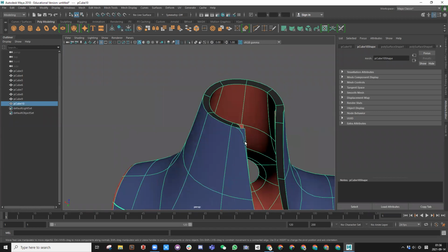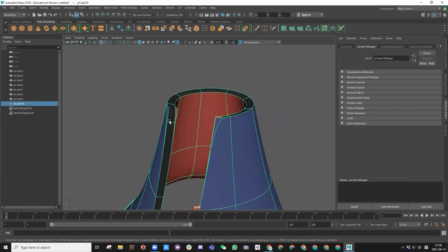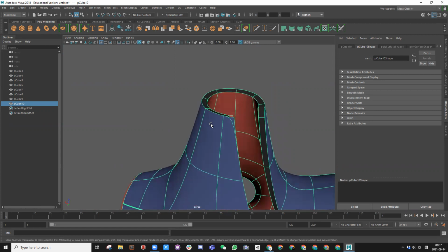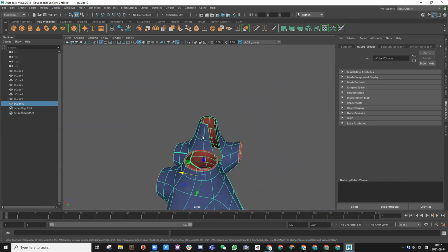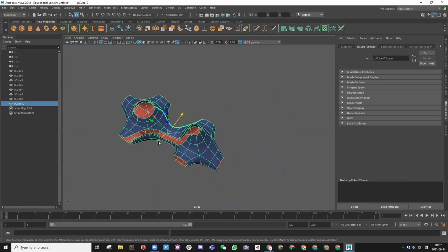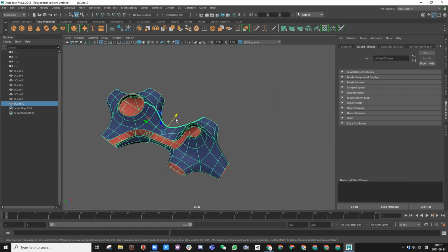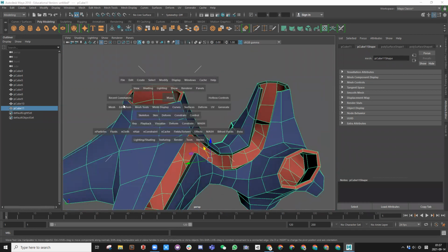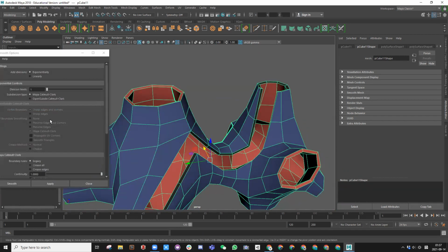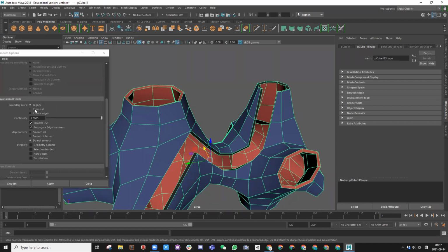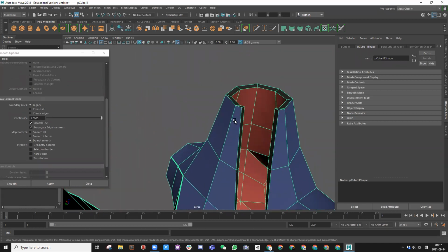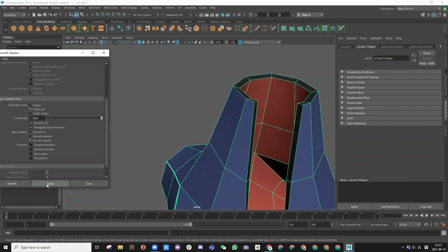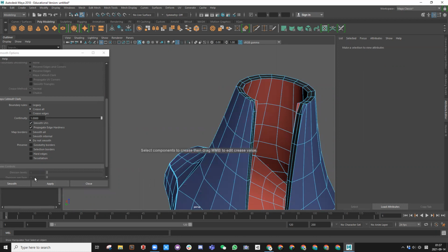If you detach it, you will see that this is a bit weird. You'll see that this is actually sharp. It's because the Catmull Clark will crease all. So for example, if you now smooth this thing, we are going to use mesh smooth using crease all, you will see the difference. If you say crease all, it's going to crease like that. So you see the same problem as your display model.